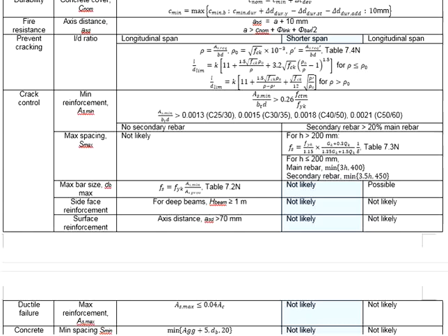The main reason is the smaller effective cross-sectional areas of the beam as compared to the loads acting onto it. When there is limited cross-sectional area and space to put the reinforcement bar, the number of reinforcement bars may be constrained.